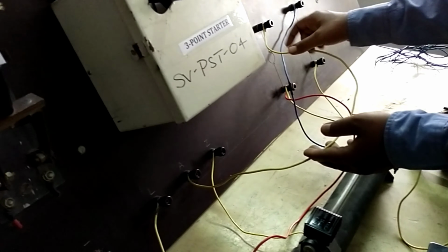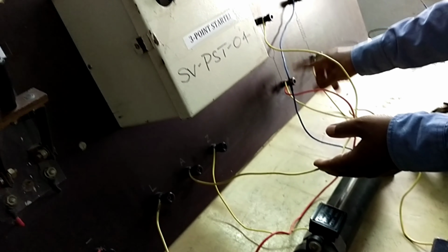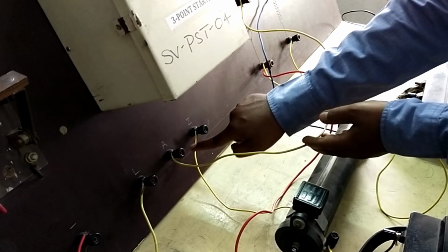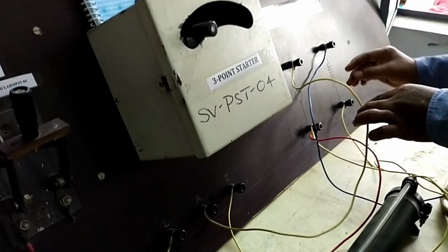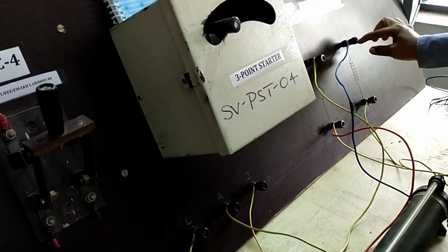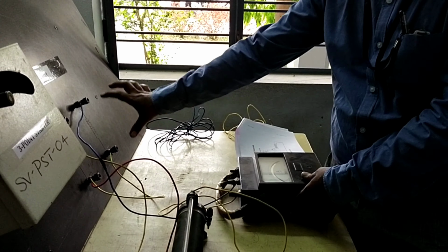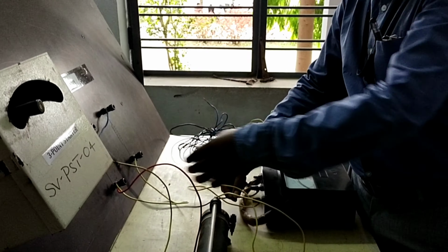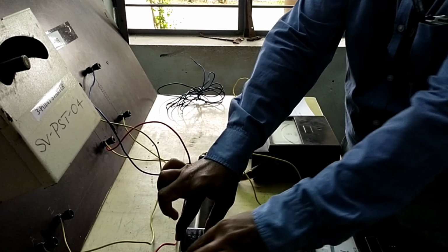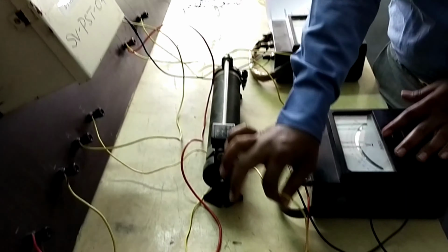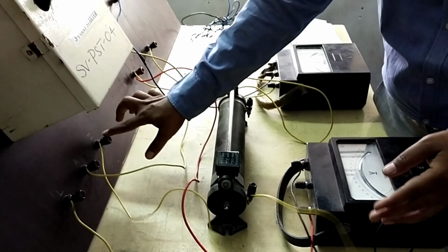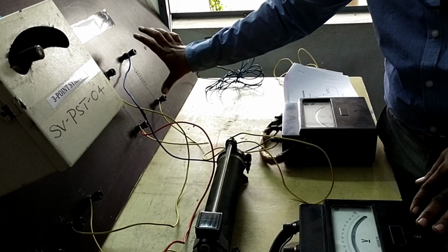L is connected to plus and A is connected to the armature. The armature terminal is denoted by A. A and double A are the armature terminals. In the 3-point starter, the A point will be connected to A. Now the Z terminal: this is Z and double Z is the shunt field winding of a DC shunt motor. One ammeter is connected in series with the field winding, double Z. This is the Z terminal. The ammeter is connected to the rheostat. This is the field rheostat. The field rheostat is again connected to Z, and the Z terminal is connected to the double Z field winding of the DC shunt motor.